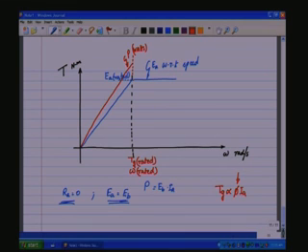So, the torque will start reducing in this zone, and the maximum that can be available is TG equals P maximum by omega. So, if we say P maximum is constant for the machine, then TG is inversely proportional to omega.